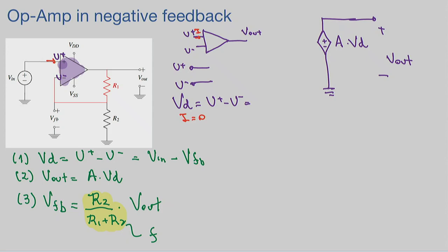Now, can we pick F? Yes. We can pick resistors. So in our model, if I want the amplification to be a factor of 3, we want an amplification of 3. How would we select these resistors here? What's the ratio that you want for an amplification of 3? With resistor ratios, come on. 1 to 2, yeah, would give you an amplification of 3.